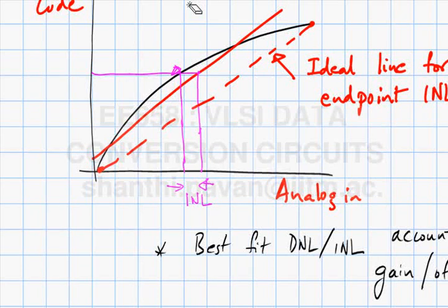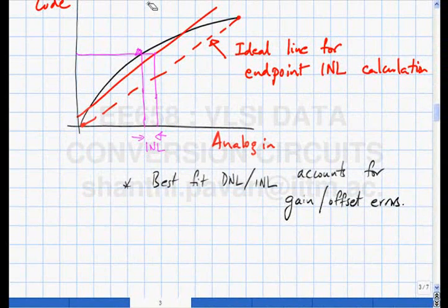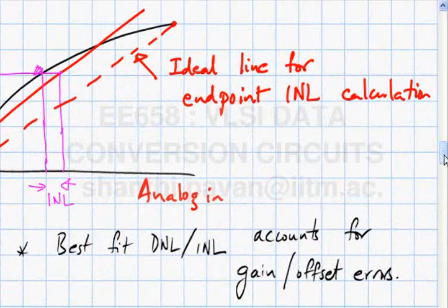What happens is that, for example, in your cell phones, the data converters involved in the signal path can tolerate a poor DNL to some extent, but if you have INL, it's possible to confuse the next channel for this. So in communication applications, you want to make sure that INL is small. Okay. So different applications have different requirements for INL and DNL.